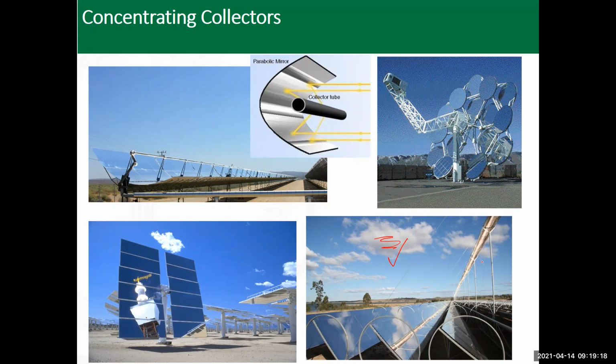So it's either you would have the water turning into steam inside the tubes, or the tube can have an oil where the oil is going to be heated, and it definitely should have some oil tank in the cycle, and that would even allow for the expansion at higher temperatures, and then a heat exchanger to transfer the heat, which is gained by the oil or the fluid that passes inside the tube of the collector until the other side where it is heated to the required temperature.